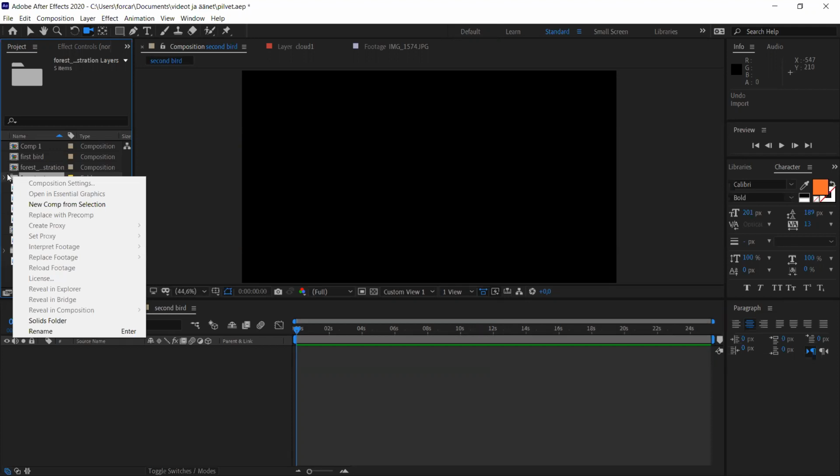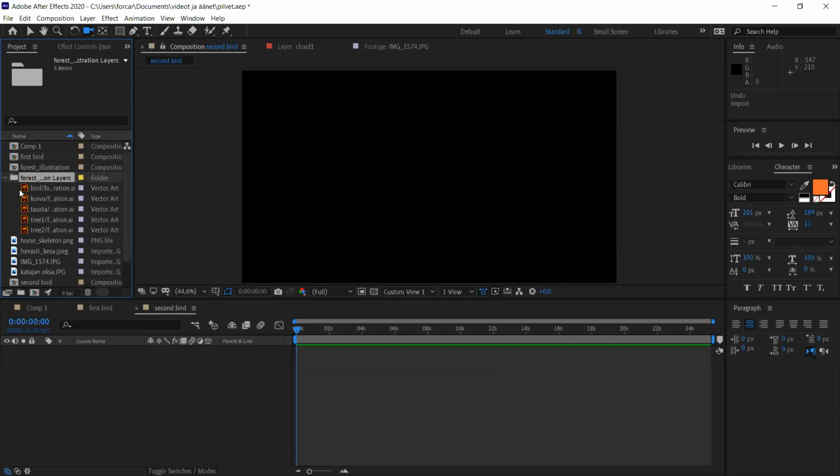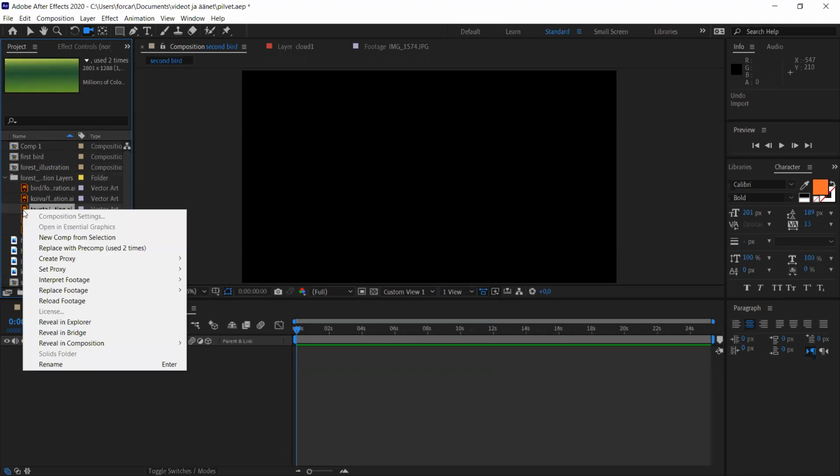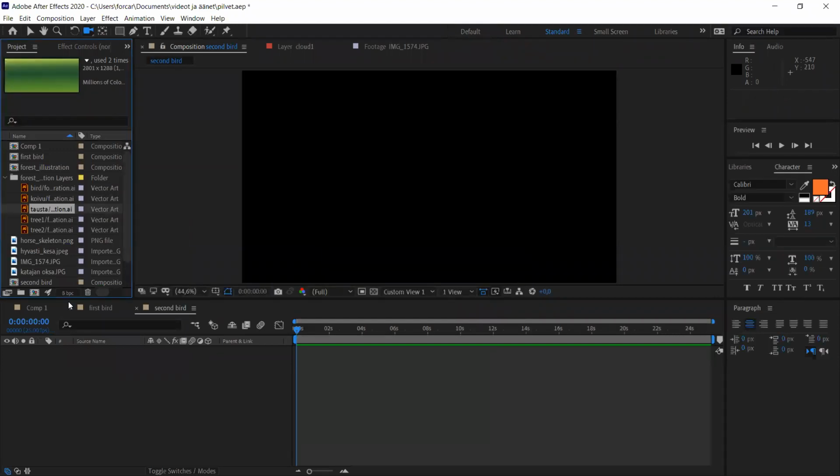So, let's say I did some changes to this background. So I will right-click there and click reload footage. And it will now reload it, refresh the image according to the changes that I made.